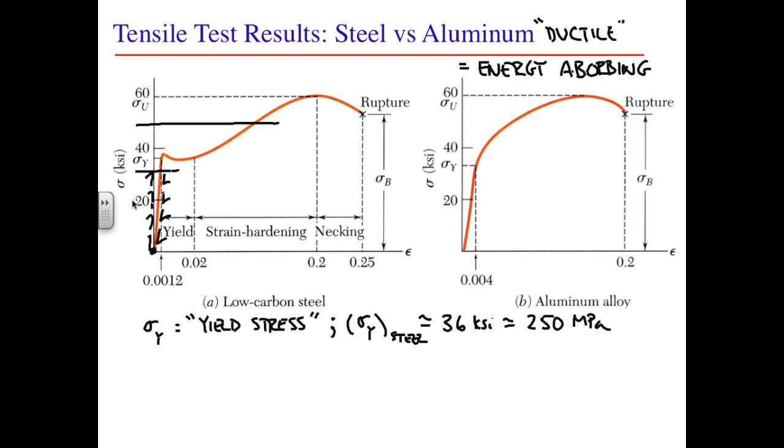As we load this up, it would climb this stress-strain curve to this position. And now when we unload it, we have an elastic unloading. We have a slope parallel to the elastic range. And when we unload it, we come down the curve this way. In this case, when we get back to zero load, we now have a permanent, irreversible deformation.